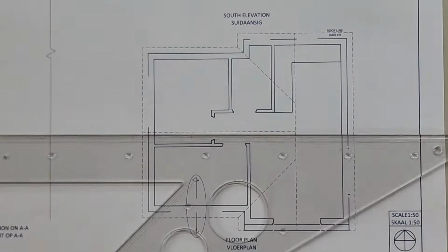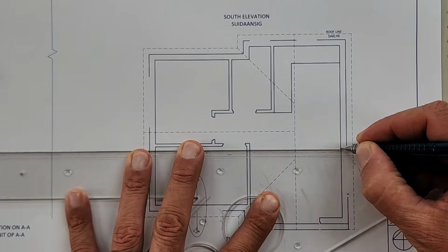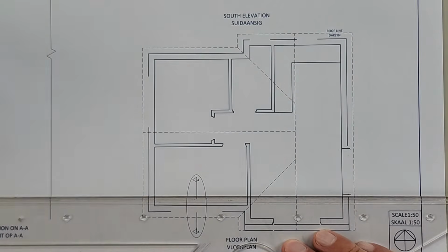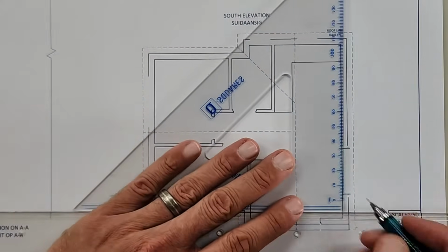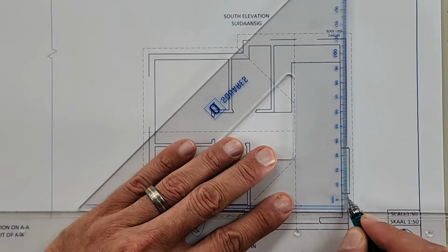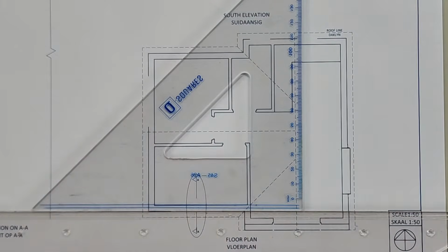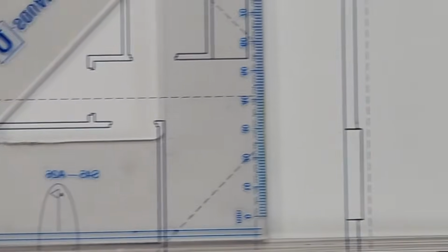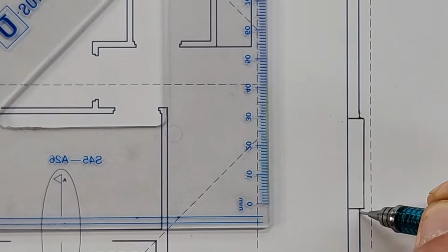Can you see that they've given you more in a gap there? So that will always be the case. What learners that are in a rush here don't do is they don't measure and they are caught out, and you will be losing marks on this drawing. So you want to show a pencil line on that end and a pencil line on that end to show that you are understanding. Let me show you there. Take a nice look here, please. There we have it. That space needs to be filled with a pencil line, okay?